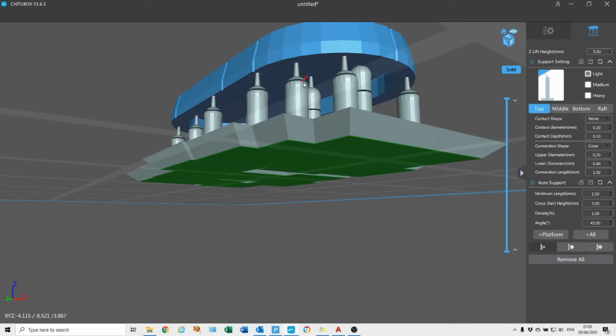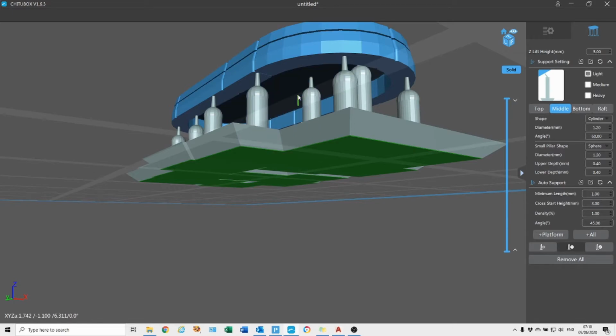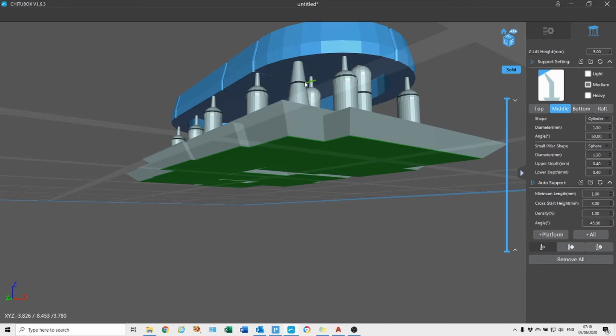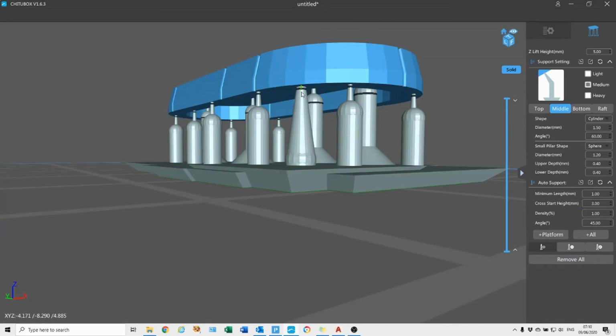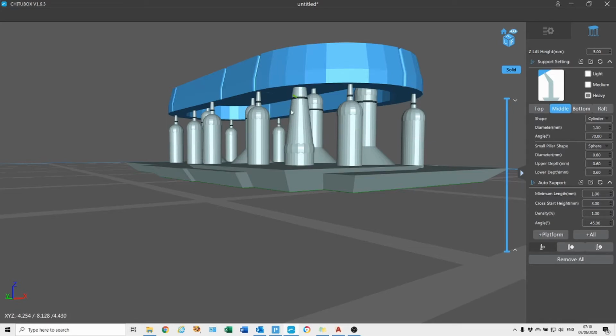So if I press it up now, it puts in a lightweight support. And if I delete that, delete, delete, delete, right. So if I delete that one and change it to medium, go back to the add and put that in, you can see that it's a slightly different style of proto for the support. And if we delete that one, delete, and we go to heavy supports, and we put one in there, go to the plus, and again it's an even thicker support.